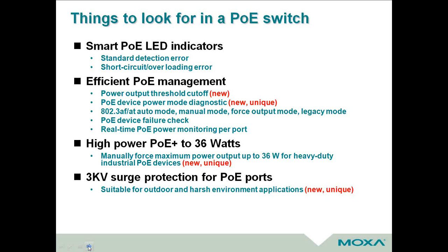You should look for switches that have the ability to do PoE plus and maybe just a little bit more than the standard, like up to 36 watts, because sometimes those power-hungry devices are not quite following the spec 100%. And maybe even look for those injectors that go up to 60 watts just in case as well. And lastly but not least, make sure it's industrial.